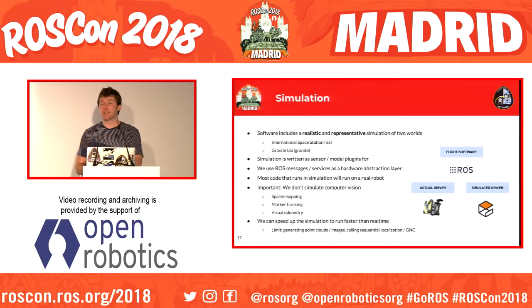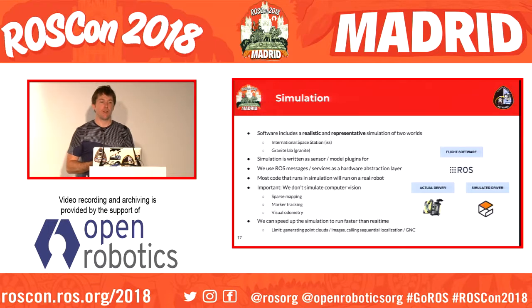A big test environment, though, and something we insist all of our project partners do before they get into working with us, is testing in simulation. The takeaway point with simulation is that we've tried to design our system such that we can divide our nodes into hardware drivers and flight software drivers, and transitioning from experiments to simulation is just as simple as switching out the hardware drivers. The only exception is that we don't simulate any feature detectors on synthetic images, because we feel that's a bit high in complexity and probably doesn't add much value.